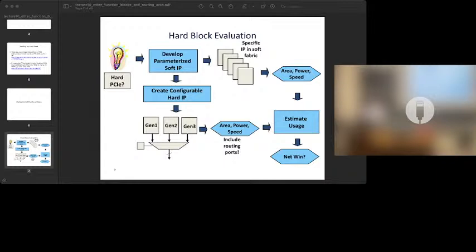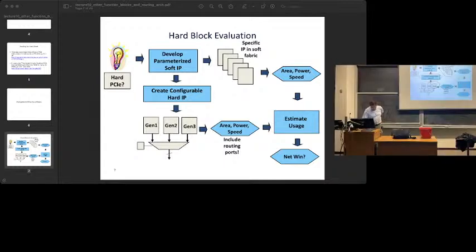But for these hard blocks, like say PCI Express, if the static power is significant, you can put what's called a sleep transistor on it. So you put a high threshold voltage transistor that's very big between the whole block and the power rail, and you put the whole thing here, like PCIe. By turning off this high threshold transistor, which will not leak much, right? That's why it's higher threshold. You basically cut the static power of this too.